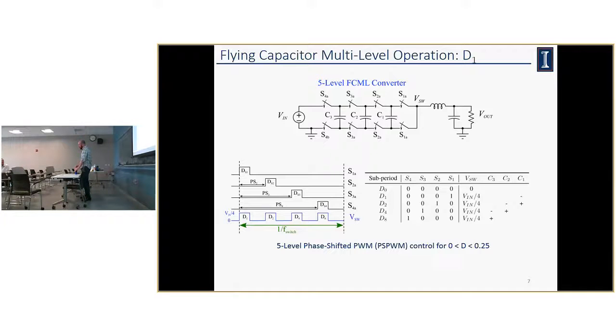If you look at the work on natural balancing, it's not intuitive at all. It uses a lot of math that proves that it works, but doesn't give you a lot of intuition on how to apply it, or a lot of rules of thumb as far as if this happens, then this happens. The capacitors are related. If one goes out of balance, it should be reflected in the others, but not in a very analytical way, I would say, especially once you start going up to a 5 level or a 7 level, that you would have a one-to-one relationship.